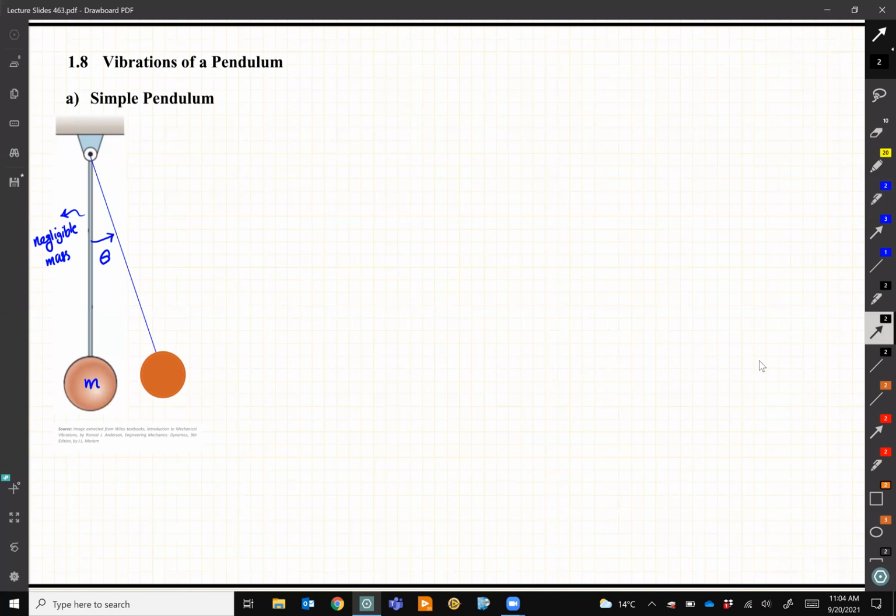The second step is drawing the free body diagram. So what I have here is a pin at O. So a pin at O, we learned that it's going to have 2 reactions. We don't know the direction of those reactions, and it doesn't matter, because even if we are interested in finding those and we are wrong in terms of direction, we just get the negative values. So I will have Ox and Oy. Let's call this joint O. And we know O is a joint. This is a pin, and a pin lets the system freely rotate. So it's just resisting X and Y.